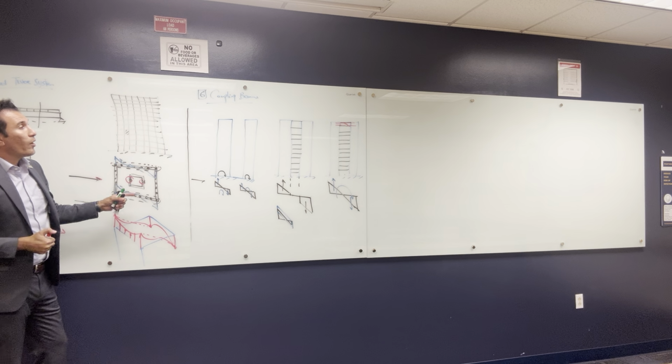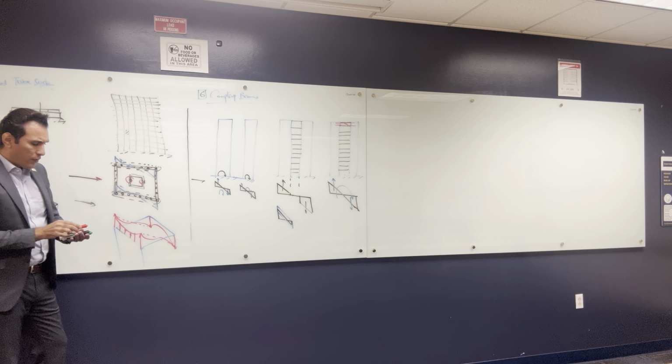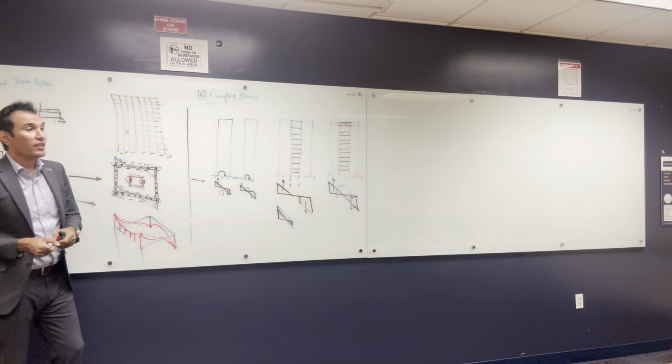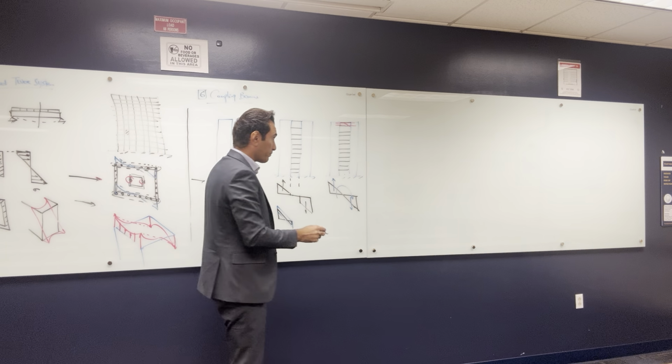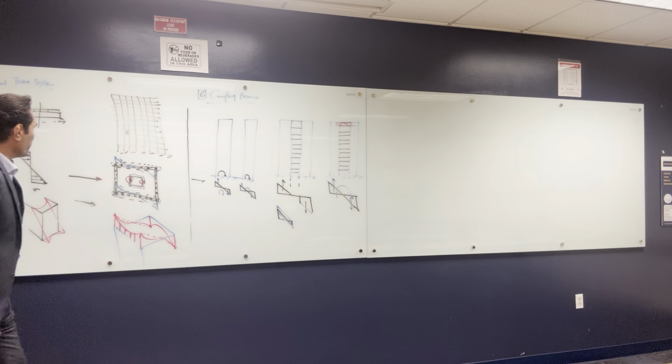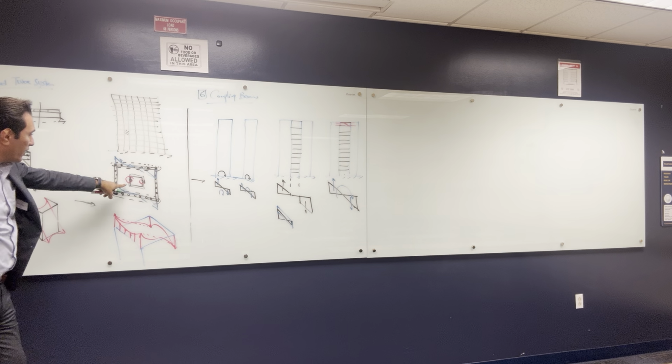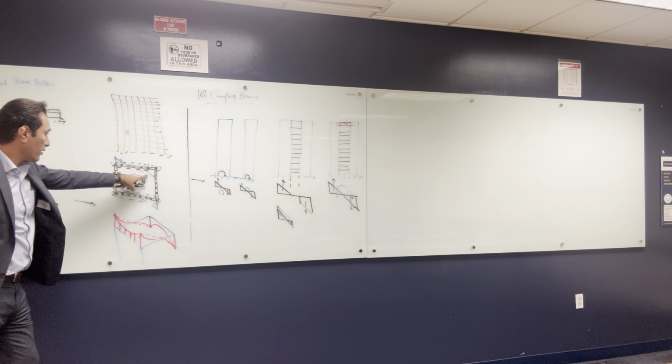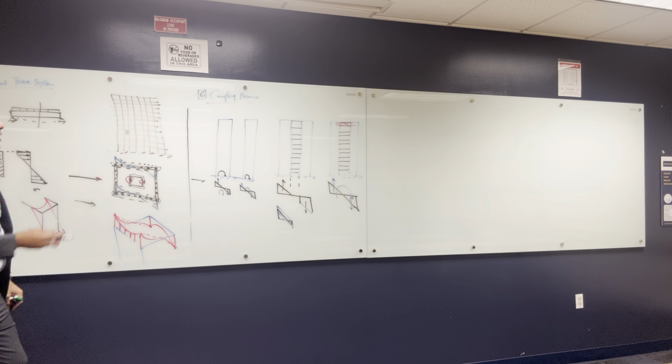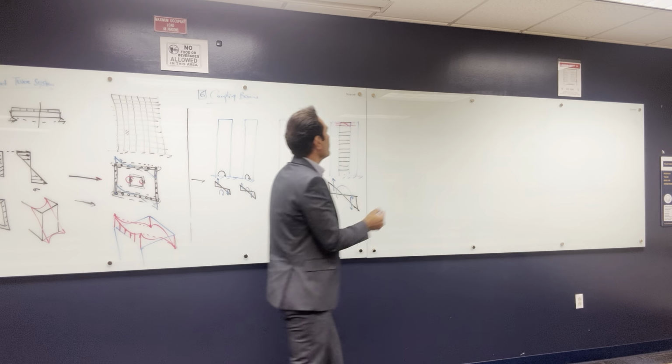All right, so is there any other systems that we need to learn about? Yeah, there's actually another way to decrease the shear lag. Right now we're learning the framed tube system and how we make a tube in tube by making another shear wall in the middle. And there's something called the bundled tubes.